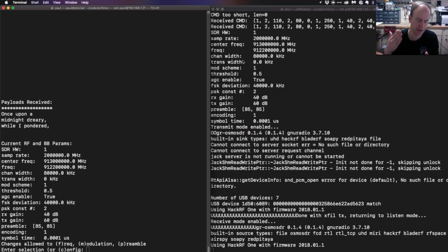So you're generating 8 megabytes per second just to look at 1 megahertz of spectrum. If you want to look at 10 or 20, which is pretty common when you're trying to seek out a signal, at 20 you're talking about 160 megabytes per second. Oftentimes you think of video as the thing that consumes the most data, but IQ files are crazy.